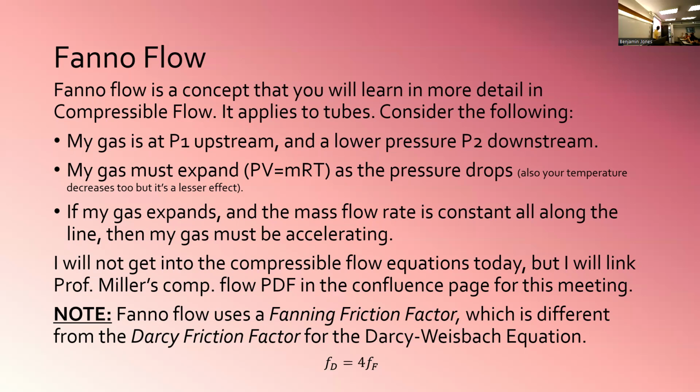I've linked the CompFlow PDF for calculating Fano flow equations if you're interested. And a very big point is Fano flow uses a Fanning friction factor. It's similar to the Darcy friction factor. It's often considered to be 4 times less than the Darcy friction factor. You do have to be careful about what factor you use. I recommend researching beforehand what number to use, but understand they are different numbers.